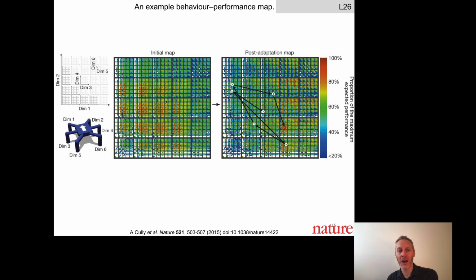Okay. Here's a picture of what actually happened. As the physical robot started acting in its environment, this was the robot's understanding of how all the various controllers would work. The robot started with this controller over here, which is, if we go back over here, where the most red was. This was the one most likely to work. You'll notice, actually it's hard to see because of the circle here, but this area became cooler afterwards. This controller did not work. We're not seeing the confidence space in this case. It went over here next, which, as we can see, has high heat over here. That controller also didn't work. So it cooled off this area and increased its certainty about things in this region.